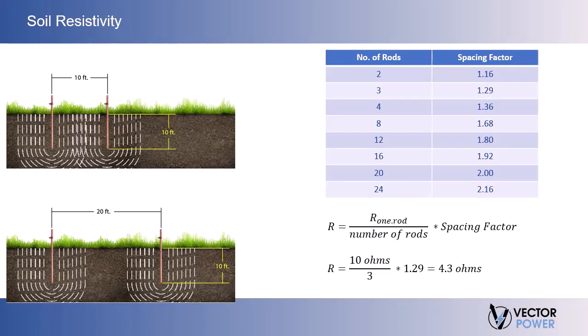We may want to use multiple ground rods rather than a single rod driven to a 32-foot depth. There are a few important points to consider when driving multiple rods. The first is that driving additional rods will not achieve a linear result. For example, 3 10-foot rods will not yield the same results as a 30-foot rod. We need to apply an adjusting factor.